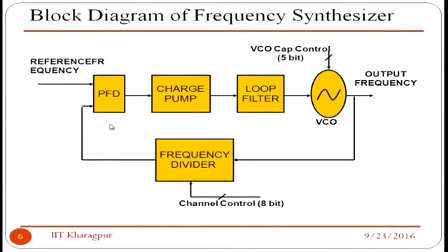So that is the 2.4. Then what will happen? I want to make it go to the next one. So I will increase my counter from 480 to 481, and so on. So you will divide the same way, suppose this is 2.401, divided by the next N plus 1, and then again it will be 5 megahertz because of the 5 megahertz spacing. F reference times N plus 1 will be your running frequency, that is the VCO frequency.